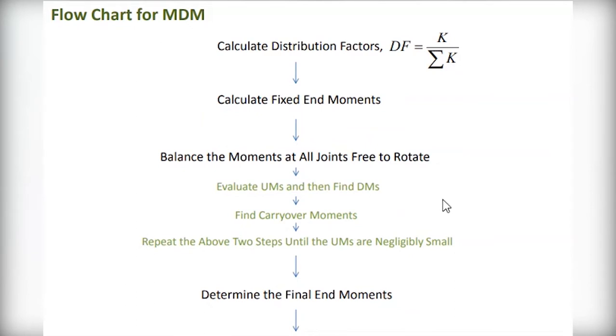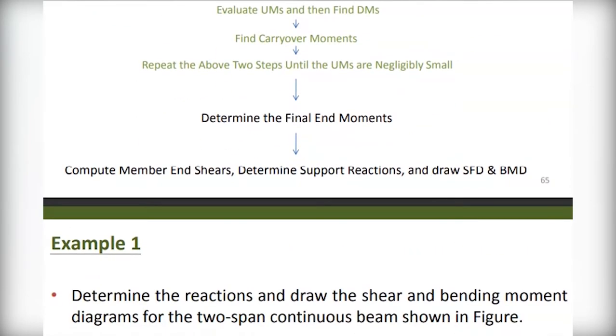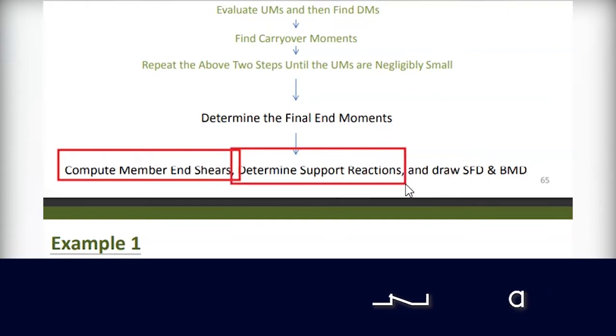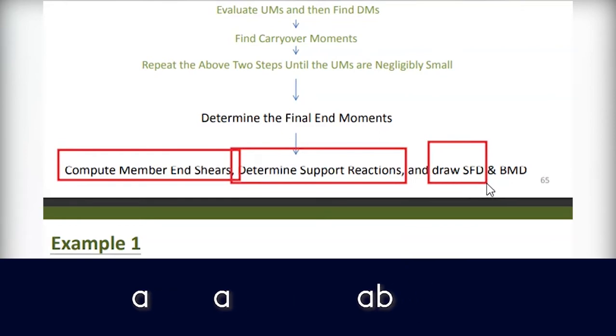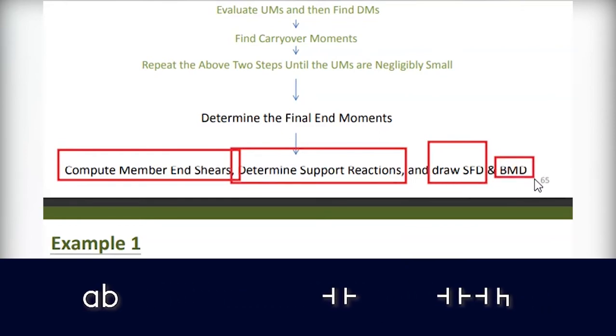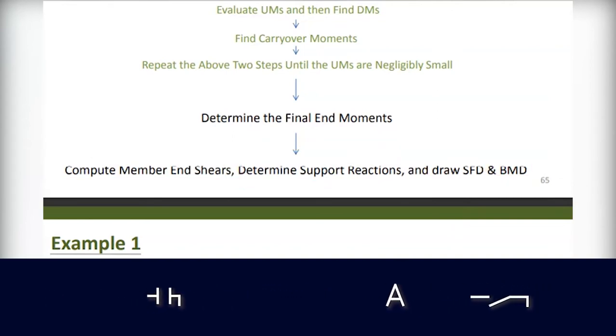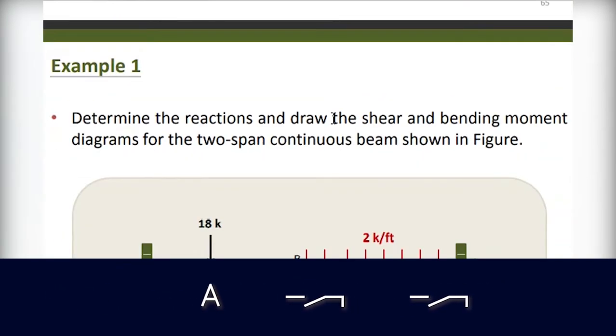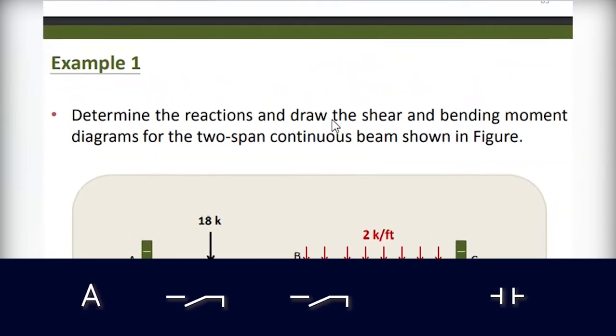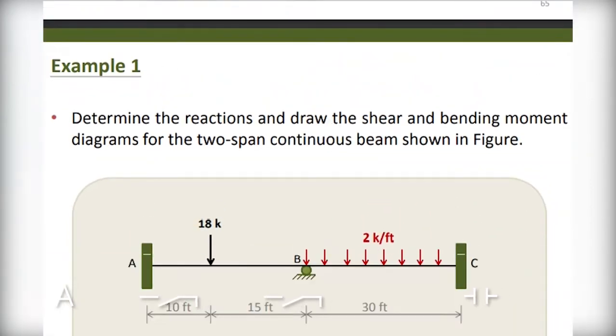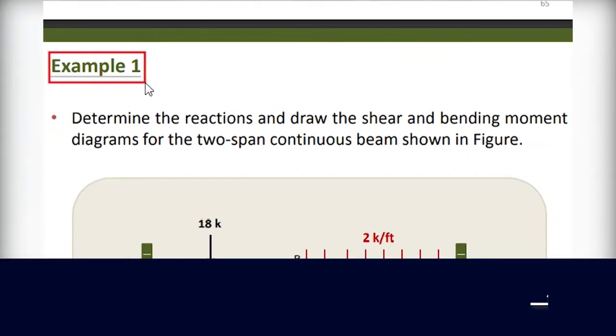After that, you can compute the shear force and determine the reaction of the support, and then you can draw the shear force diagram and the bending moment diagram. Now let's have an example in order to be clear on these procedures. Now let's have another example.